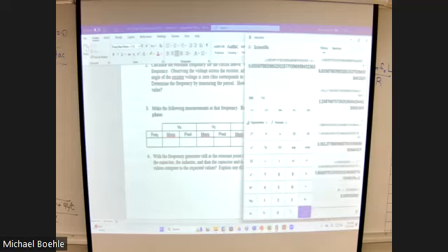And you might even see a little bit more because the interaction of the resistance from the function generator is not always really that much. So maybe the Q is a little higher, maybe you get a little bit more than 9 volts. But you should get about 9 volts. And because you set the phase shift to 0 degrees, you should see a nice, perfect, negative 90-degree phase shift across your capacitor.